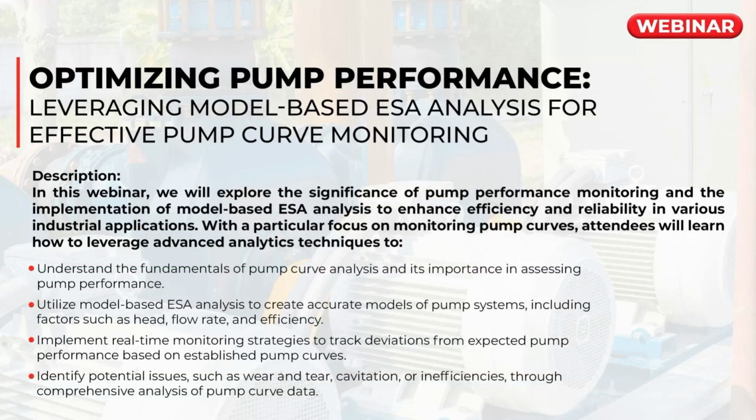We also look at how we merge this information with the existing electrical, mechanical, and process fault detection capabilities of model-based electrical signature analysis, and then identify potential issues such as wear and tear, cavitation, or inefficiencies through comprehensive analysis of pump curve data, again, with a combination of electrical and mechanical faults.